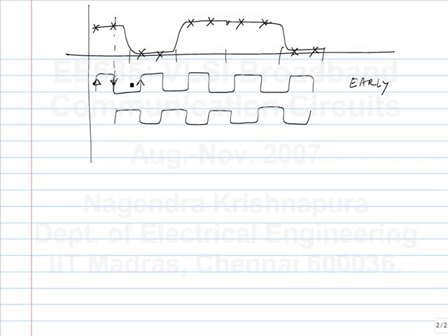You want to align the negative edge with the transition. So you take the samples of the previous positive edge and the following positive edge. You have a negative edge, and on either side you have rising edges. So you take the sample at the falling edge, the rising edge before it, and the rising edge after it. From that you will be able to tell.